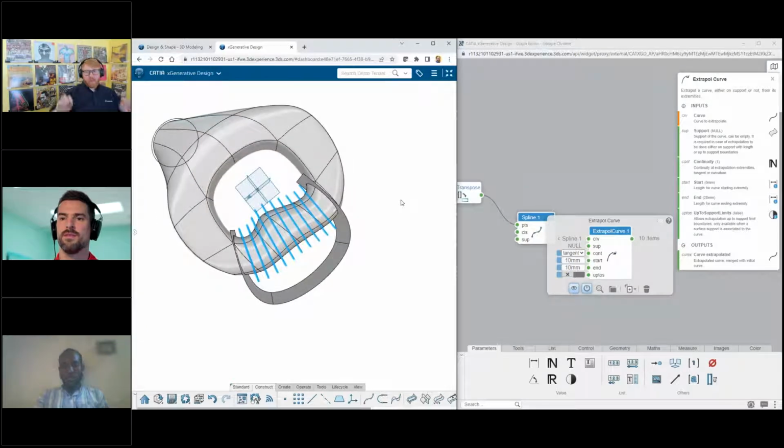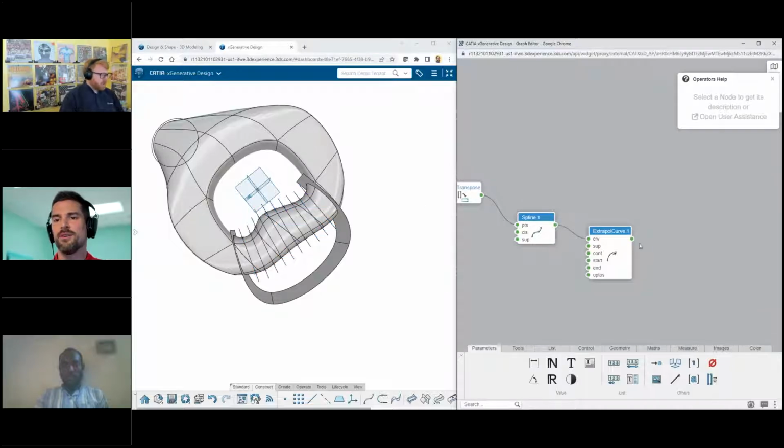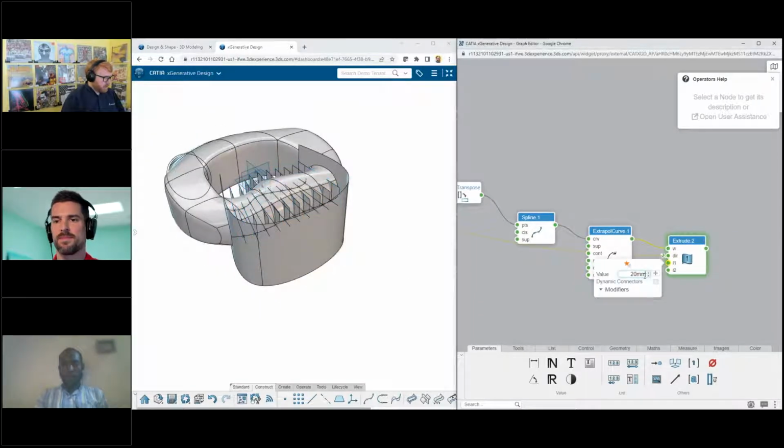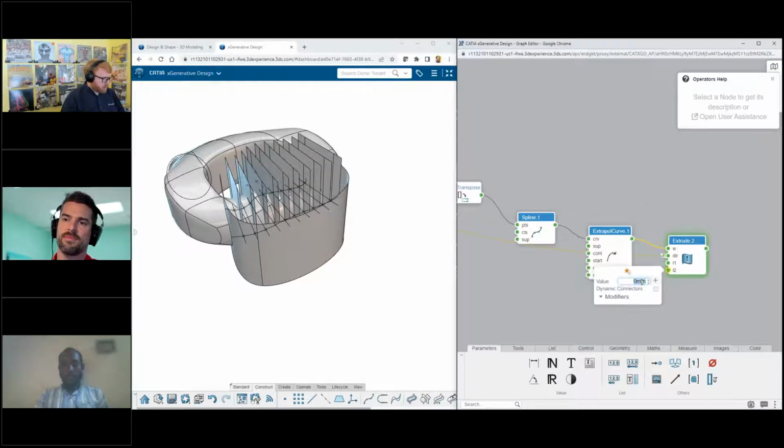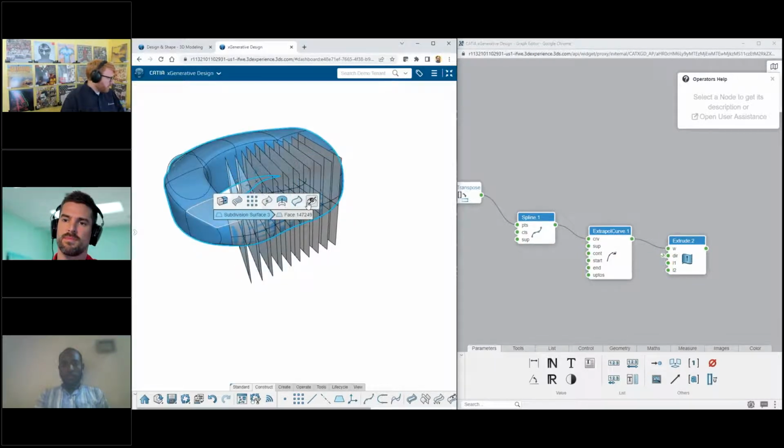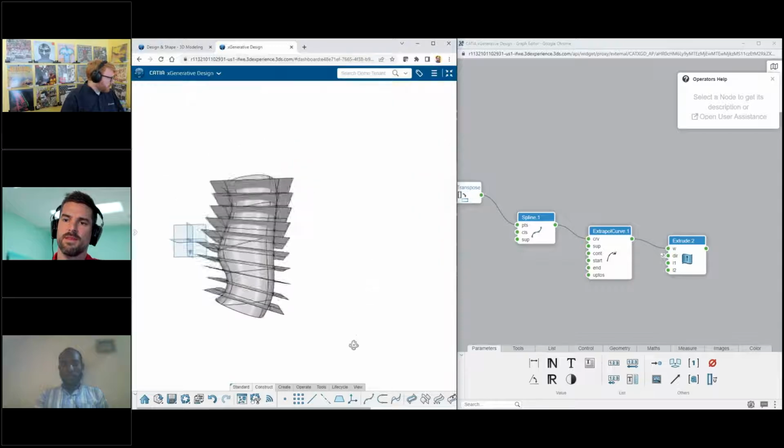We could also do it with, you know, you do convert entities and you drag the line away to make it a little longer, but still the same thing. So this way you're extending it past the extents of the underlying surface. Right. Exactly. Good. So now I can say I want to go up by 50 and we'll go down by 50. And this is getting a little confusing, so I'll hide this and I'll hide this. Now we can just see what I'm working with here.